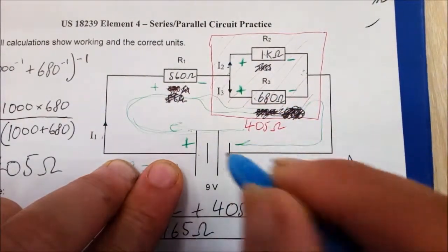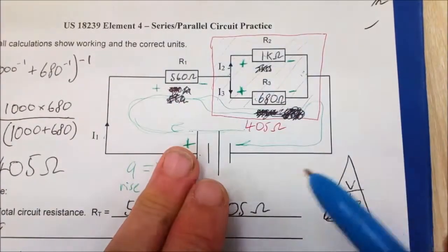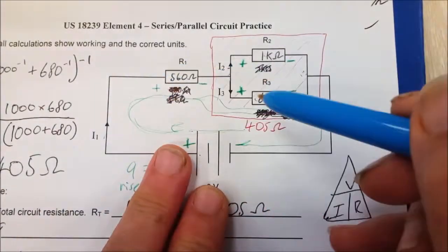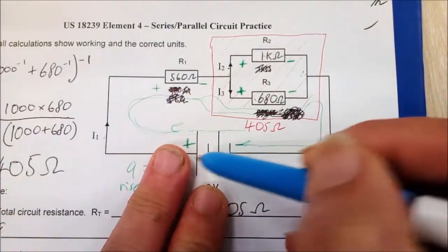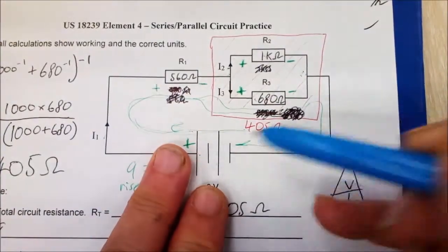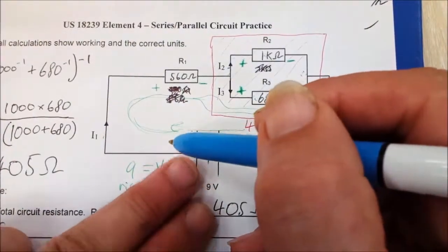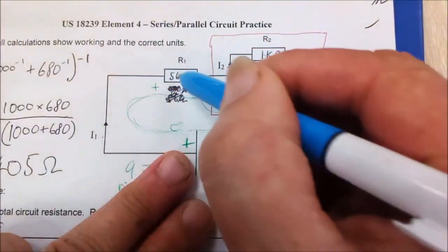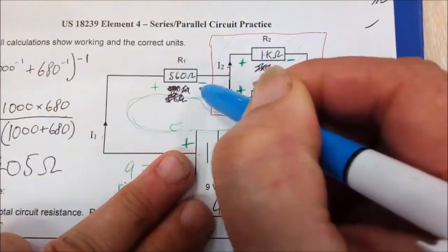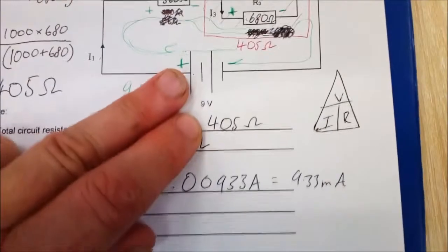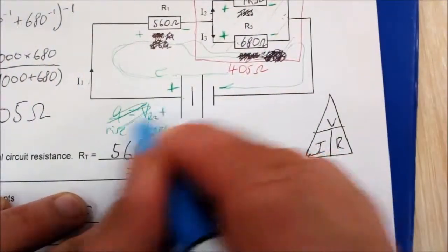Okay, so we're going through the battery, which is a rise. Battery is 9 volts. Now, the sum of the voltage drops around a circuit should equal the voltage rise, or sum of voltage rises. Okay, so we've gone through this 9 volts, and on the other side we have, firstly, this voltage here, a voltage drop. Now we know that, we've calculated it, and it is down here. That's VR1. In fact, I've made such a mess of this thing, I'll do it again.